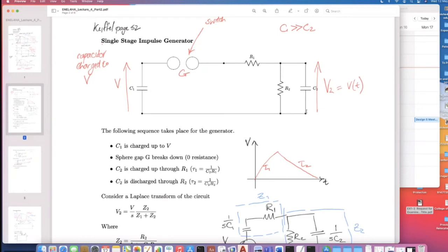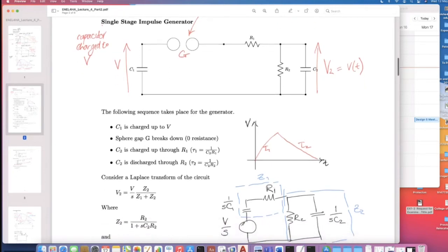That means that the voltage of that C2 will increase. Once that's fully charged, or there's a balance, C2 will then discharge into R2. As it discharges, the voltage goes down. There's an approximate circuit there that tells you what's going on. We've got a charging time and a discharging time. That makes sense to everybody, I hope?